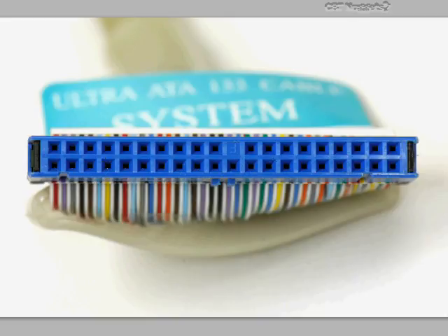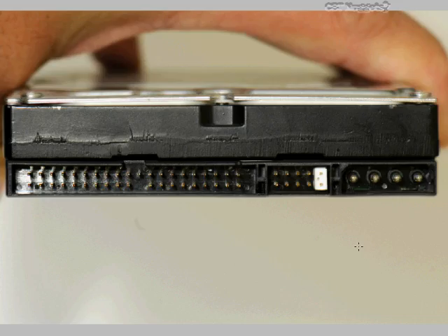And you can see, if you want to count them all up there, there are indeed 40 pin positions there. But if you were to look at these colored wires here, there's actually 80 wires there. The white ones are the ones that are designed to help protect from crosstalk. And then the other end of the cable, where you actually connect it to the drive, would go on these 40 pins that we see over here.